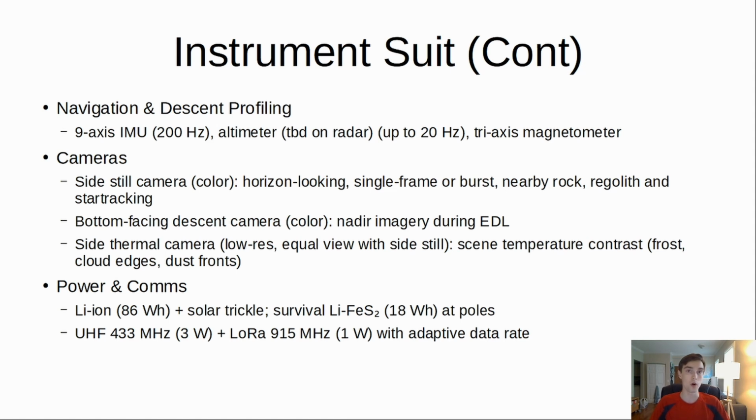Of course, all of this data is not very useful if we can't power the probe and transmit that data. So right now we have 4 lithium ion. I want to change to nickel metal hydride. Those are my favorites. I likely will in the end, even though the specific energy of them is far lower. They're much better in terms of cycle performance and temperature performance. Mostly that low temperature. That's what I really care about.